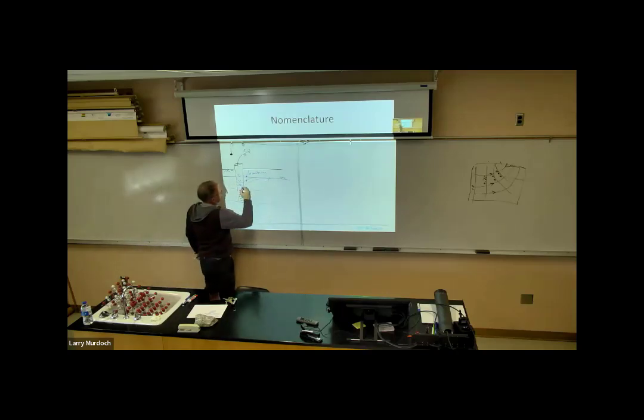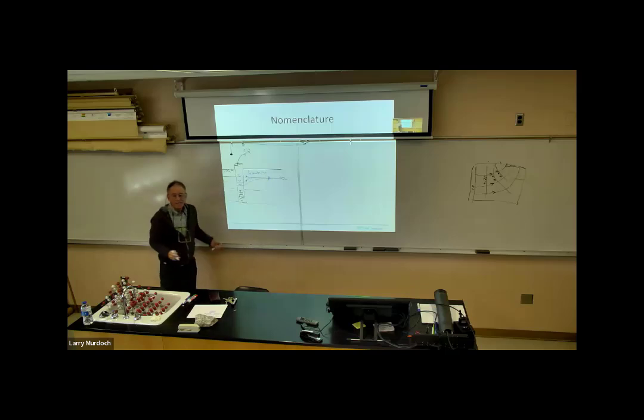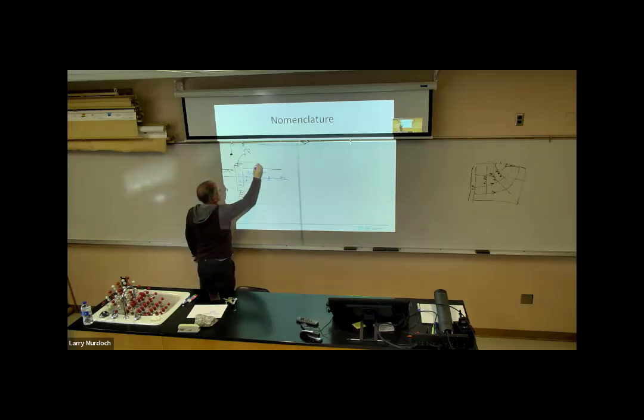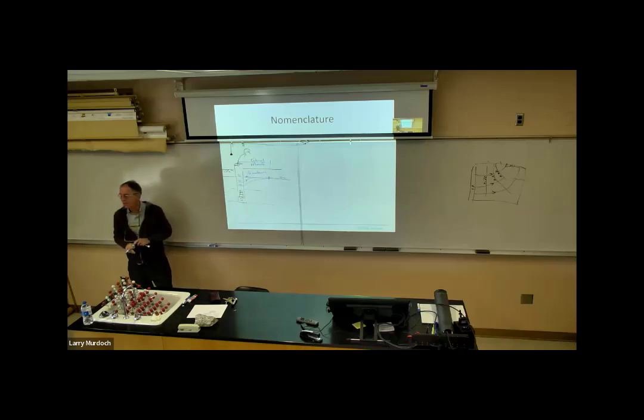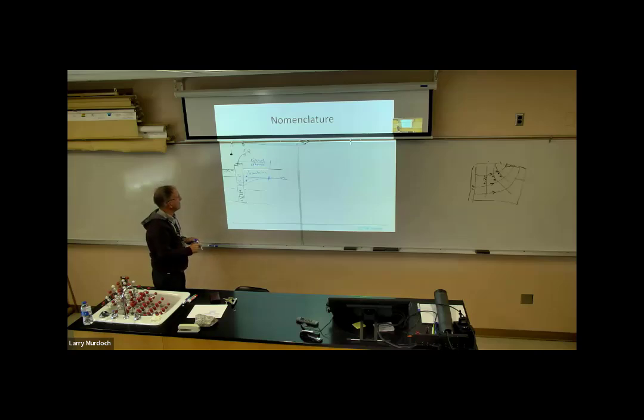So we see that the well is causing drawdown out to a distance here, but out beyond that distance, there really is no effect. There's no change in the water level. So this is the radius of influence. That's going to change with time. So radius of influence will increase.